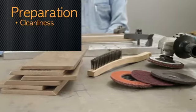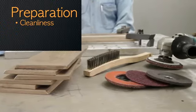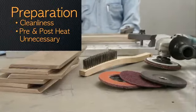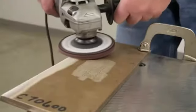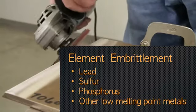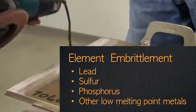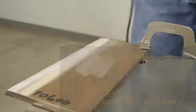Maintain a high level of cleanliness and avoid contamination, which can cause weld cracking. Preheat and post-weld heat treatments are unnecessary. There are elements that even in small amounts are very detrimental to copper-nickel alloys, and if present on the surface before welding, they can cause embrittlement and cracking. The elements that are particularly harmful are lead, sulfur, phosphorus, and other low melting point metals.